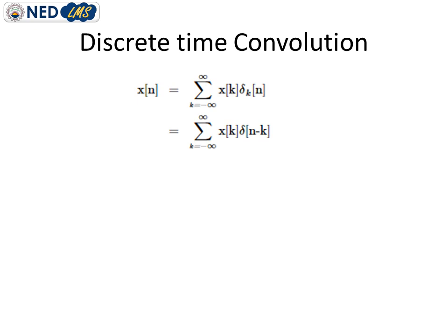The input signal is decomposed into simple additive components. Each of these components is passed through a linear system, and the resulting output components are synthesized, or we can say added. So the signal resulting from this divide and conquer procedure is identical to that obtained by directly passing the original signal through the system.